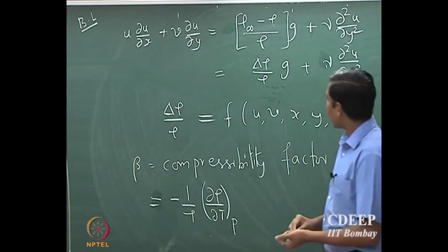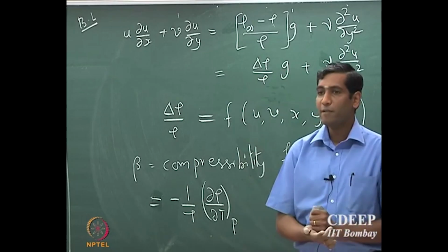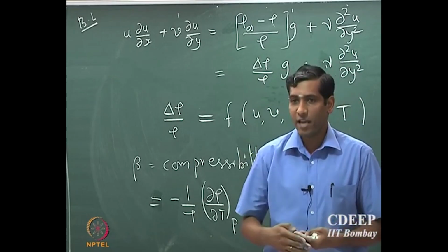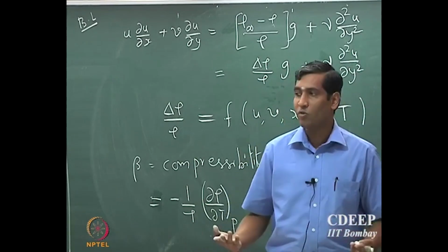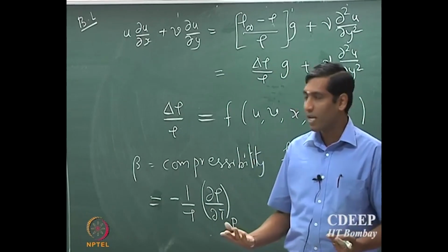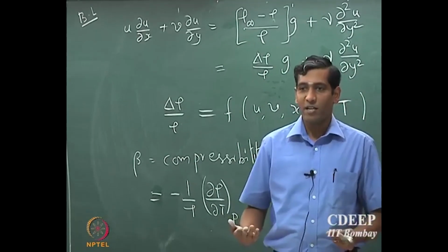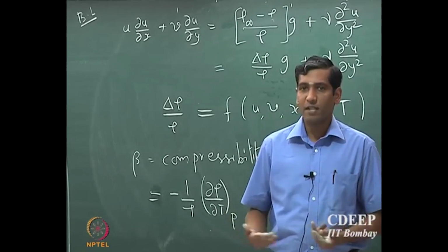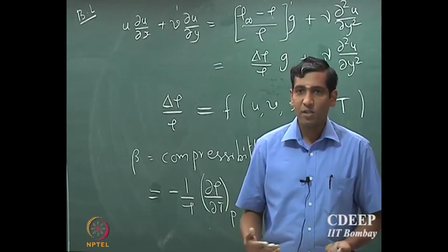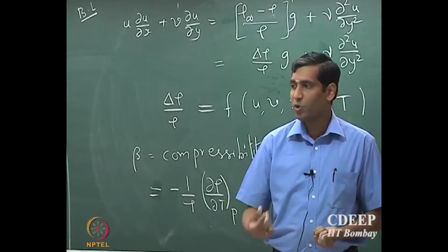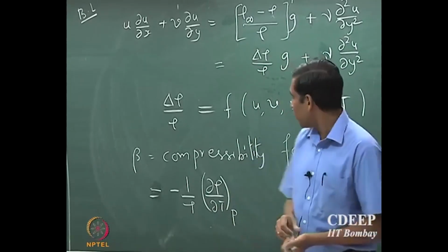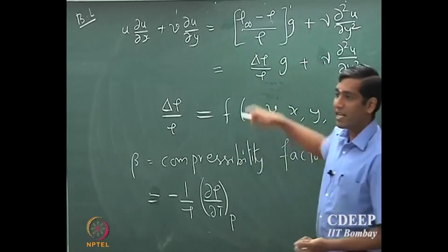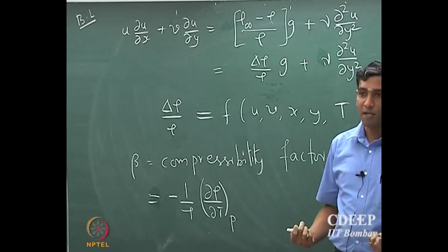Now what do you expect the density gradients to be? Is it expected to be very large compared to the density, the local density, or not? So it is not, because it is a free convection problem, there is no forced convection, and so we expect even the boundary layer thickness to be significantly smaller, and so we expect the density gradient also to be very, very small.